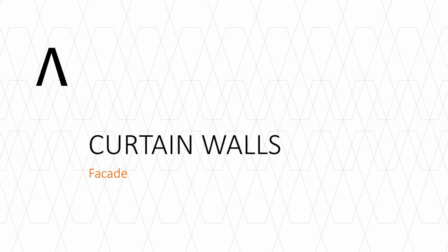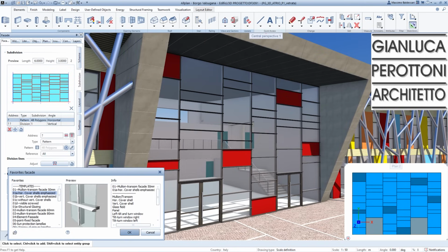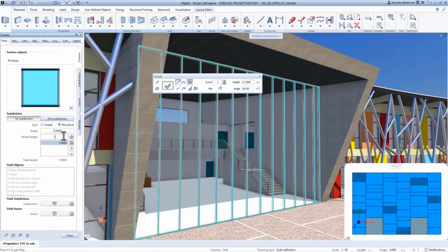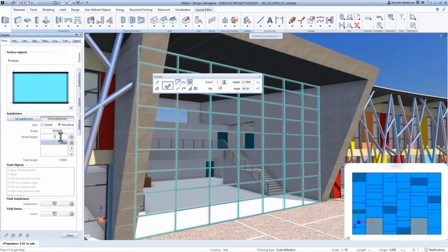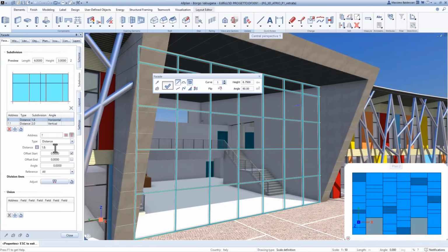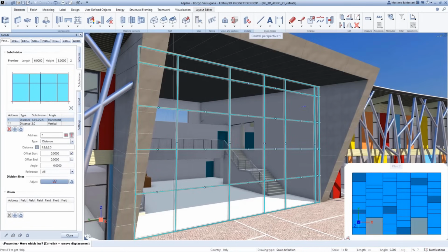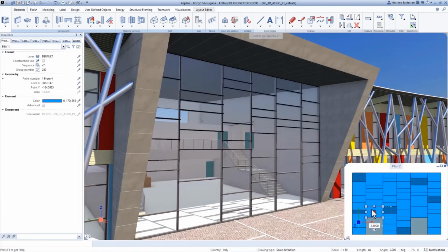As you know, facades play a significant role in modern architecture. ALLPLAN enables you to design facades in an exceptionally intuitive manner. You can divide your facade by inputting values for vertical and horizontal subdivisions, or adjust the subdivisions graphically by directly selecting the elements. Additionally, you can match an existing 2D pattern to get the facade scheme you are looking for.